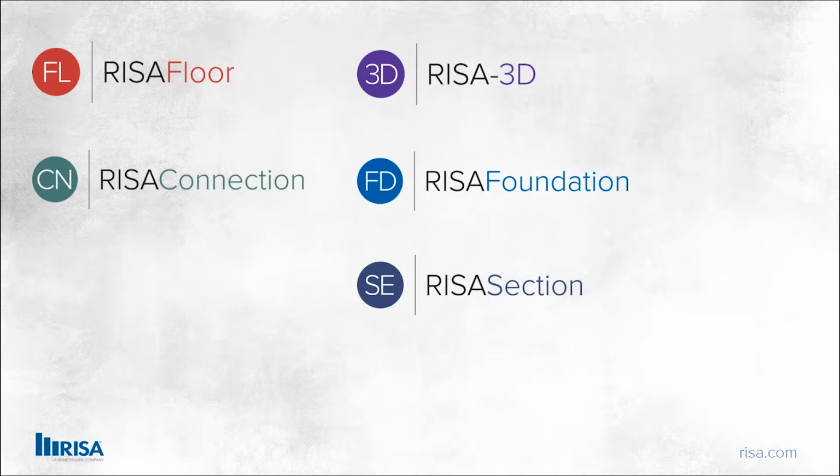RISAFloor, as I mentioned, is a building modeling tool. So we assume that there is an area load. We can do it floor by floor. That's why we call it RISAFloor, because sometimes that can be confusing, but it's floor by floor, which makes it helpful to look at a three-dimensional model one floor at a time. RISAFloor carries the loads down the structure floor by floor. And you're doing just the gravity design over in RISAFloor and taking the lateral elements over to RISA 3D for design of that. RISAFoundation also connects with these programs.